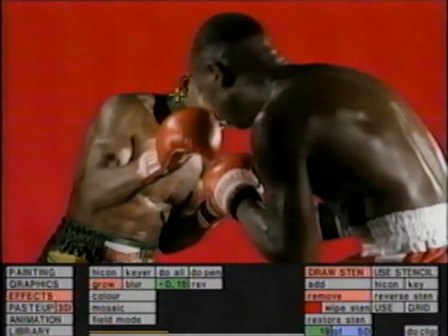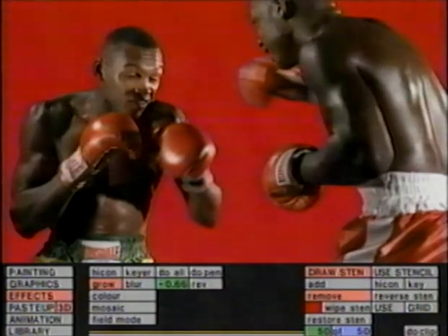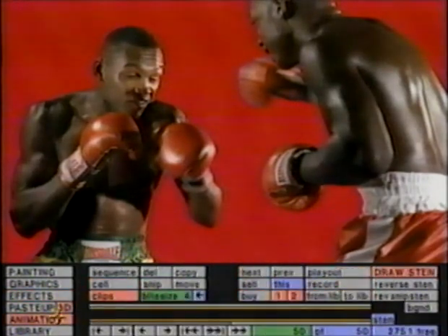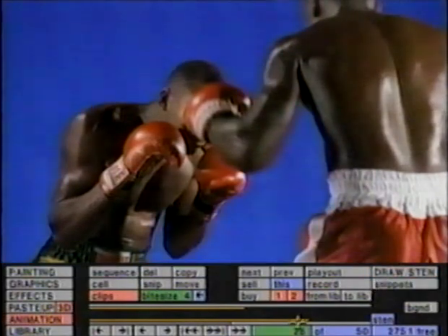The edges of the clip stencil can be expanded or contracted to deal with blue spill or to produce a soft drop shadow effect. Grow functions very much like Blur with a preview window, and Do Clip applies the grow to the whole clip. Having processed the required clip stencil, the clip can be cut, this time with its clip stencil, and keyed over a background in Paste Up.